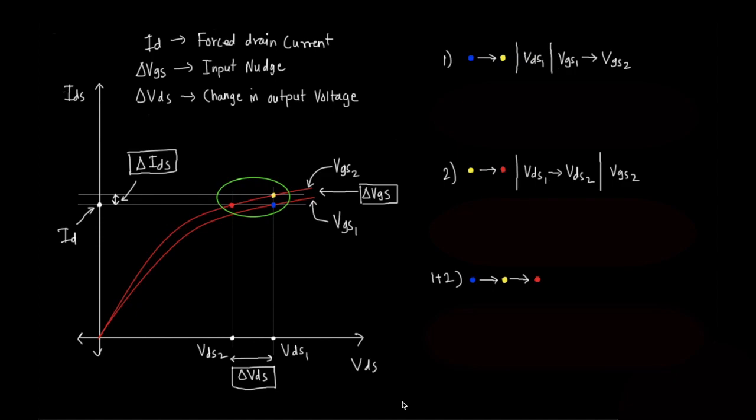What if we think about this process one step at a time? Let's think that the change in VGS causes the MOSFET current IDS to change, which we can calculate by the value of gm. While we do that, from the graph, we can see that we are moving vertically upwards. So VDS is still constant, which was the condition while measuring gm. But this change is not possible, as the value of current through drain and source is fixed because of the current source that we had put there. So now, whatever IDS has changed should get cancelled or should go, quote-unquote, somewhere else. We will think about where the delta IDS has gone soon.